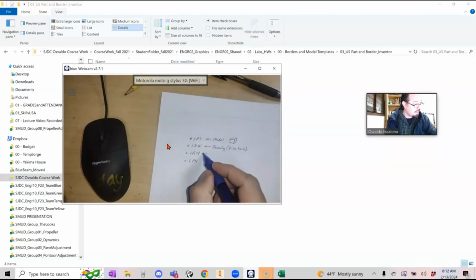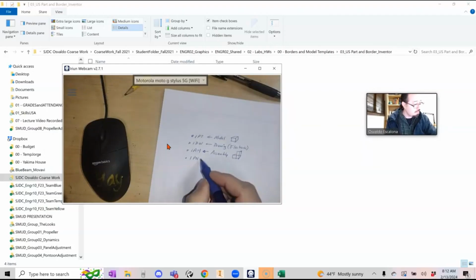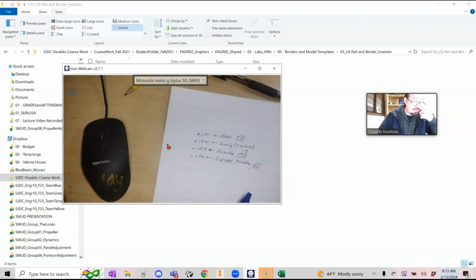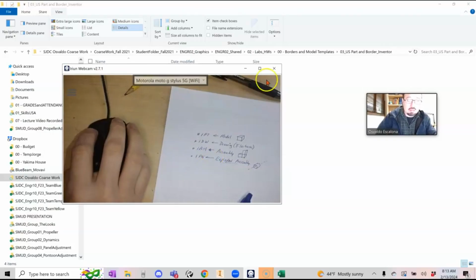This IAM is an assembly file. If you have a bunch of models, you stack them together, you assemble them, and you get an assembly. The assembly looks like 3 blocks stacked on top of each other. The IPN is an exploded assembly. It's like the assembly you see here, but it looks like a part and it has an axis. It allows you to represent an assembly and separate it to see how things are. You can also create animations for the exploded assembly. In fact, one of the main features of IPNs is that you can create exploded assemblies.